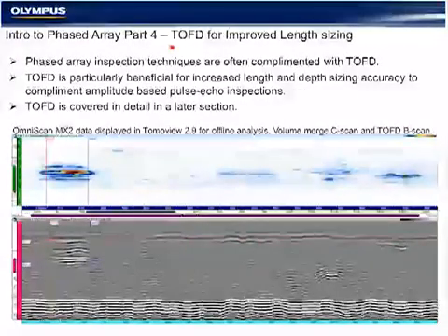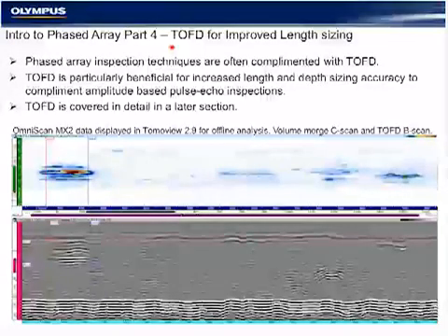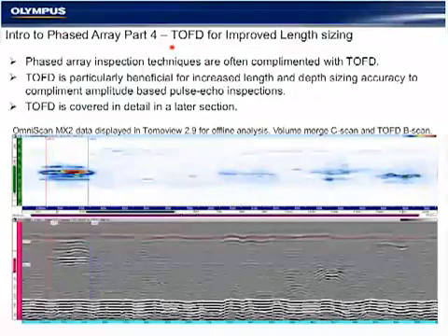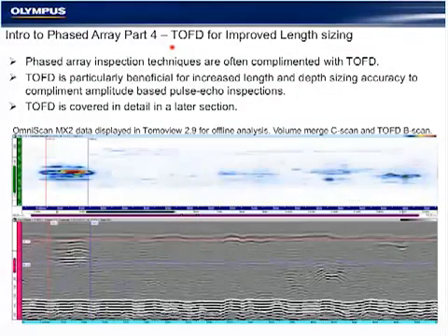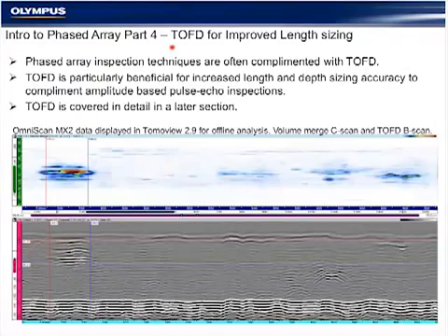And we get asked often, why do we use TOF with phased array? There's generally two reasons. The overwhelming majority of our 30-degree weld bevels can be inspected without TOF. But when the weld bevel becomes more narrow at unfavorable perpendicular angles to the inspection beam, for instance, a 60-degree beam would be optimum for inspecting a 30-degree weld bevel because it creates a perpendicular inspection interface for the bevel where most flaws occur. So we supplement that with TOF.